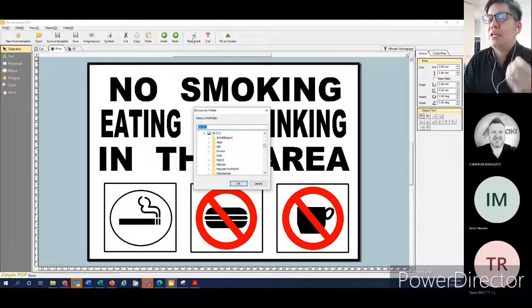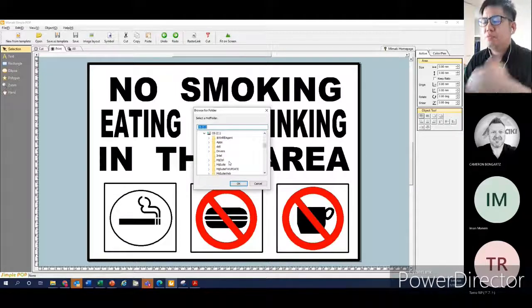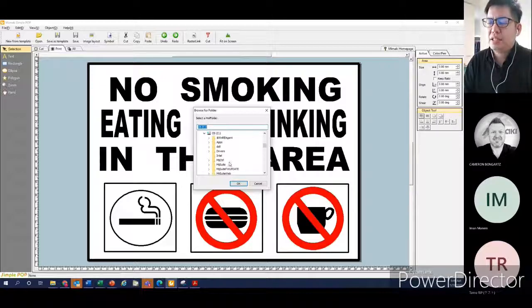So click the rastering button. You can just save this print and cut file into the hot folder, right? And then it's going to open automatically in the rastering for printing. If you do a print and cut with registration marks, you need to add registration marks in the rastering. That way you can do print and cut with the machine.